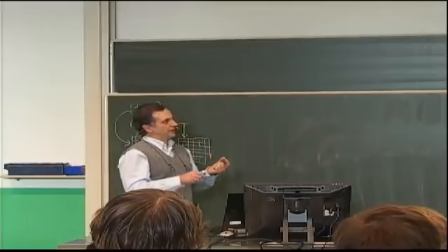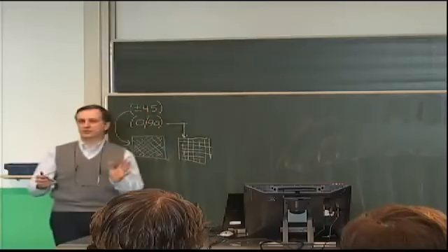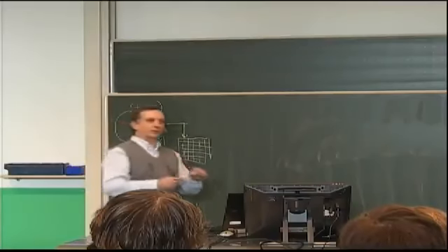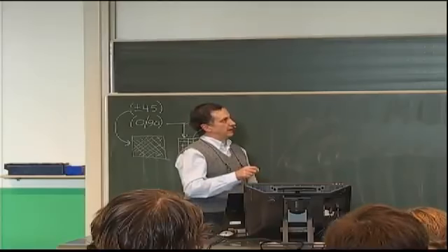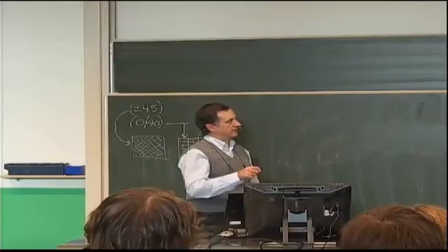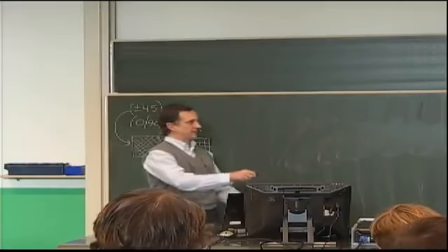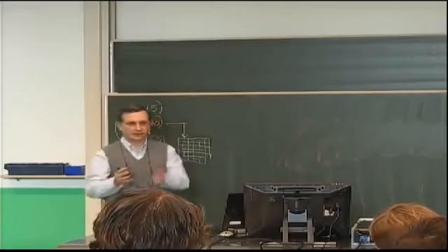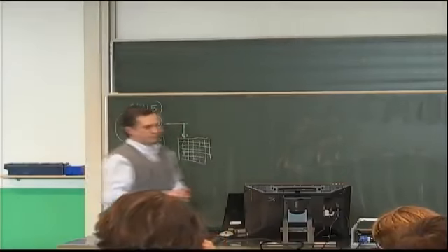So if you stay close to the x over a equals 0, that would give you the biggest sizes you would need. So unless you really want to optimize the reinforcement and make it have the widest size at x over a equals 0 at the top, and then as you move away from that edge, it becomes narrower and narrower to follow the stresses reducing, you can do that. It's just much more costly, but it's also the most efficient if you are trying to reduce weight.